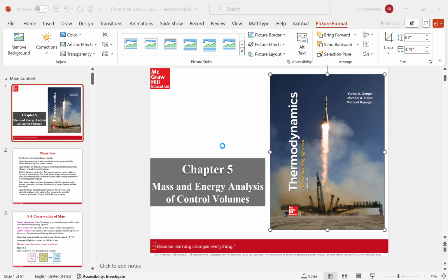At the end, you write these equations down as mass coming in minus mass going out is the change in the mass. Then you write the energy balance, taking into account the mass multiplied by the energy coming in, the mass multiplied by the energy going out, and the total change in the energy. So unsteady flow processes are typically more complex.